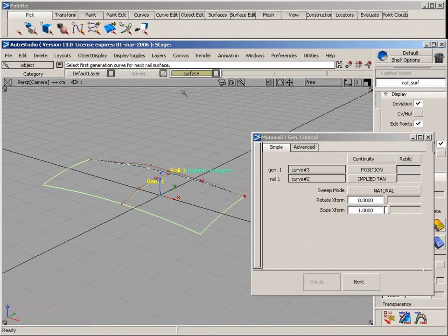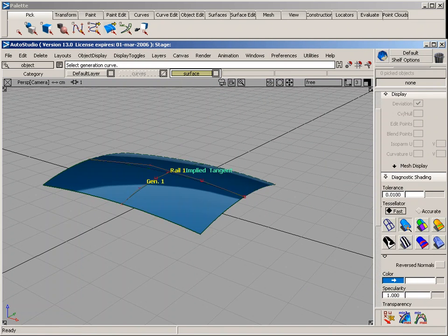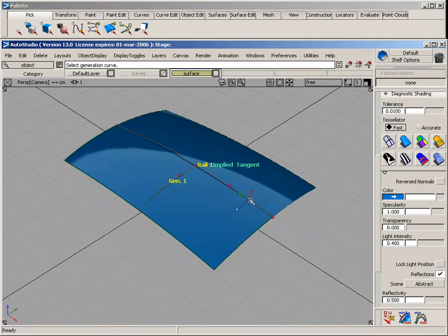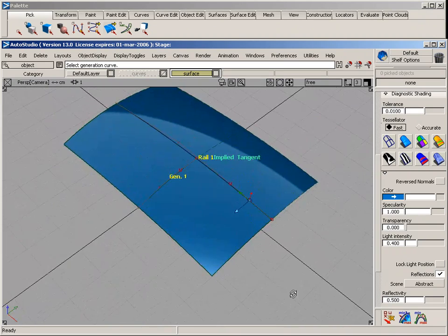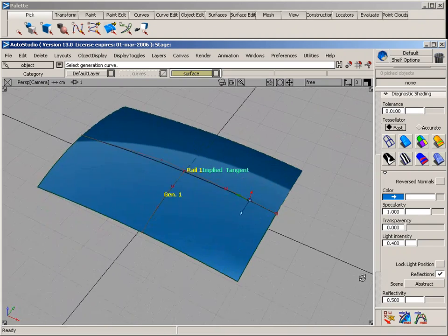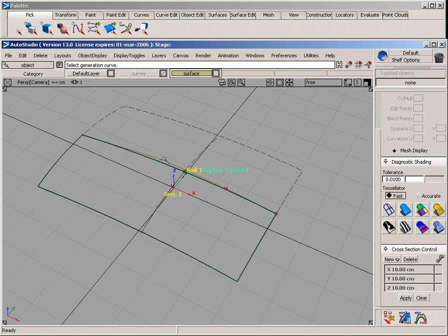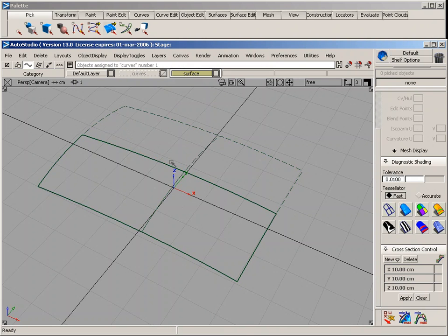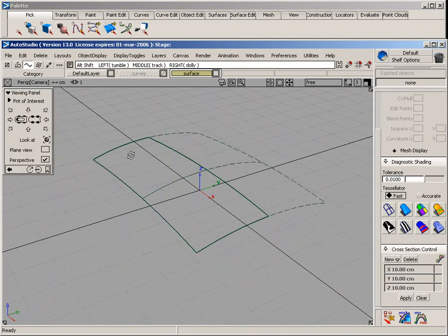Now, in order to evaluate this, I immediately go onto the Surface tool, turn on Symmetry, and make sure that there's no seams going across the center line. Once this is in place, I want to get into the habit of taking the curves that I've used, select Curve, and assign them onto the layer that is now invisible. Again, this way I can use them later on in case I need to make changes to the design.